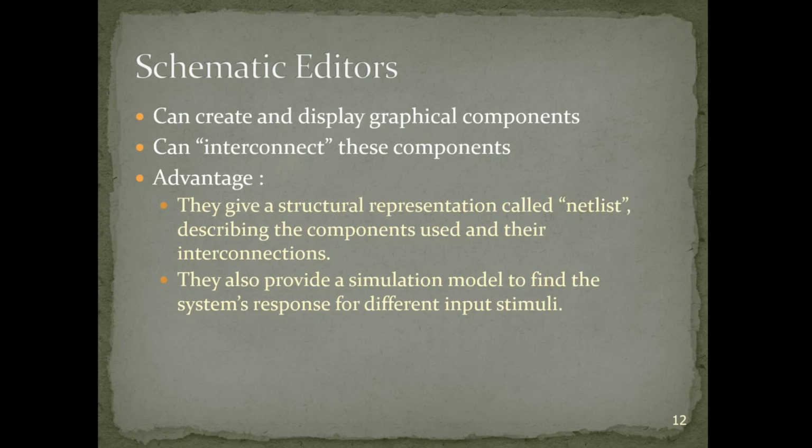What is also useful in Xilinx is that all those components that we put on a worksheet come with a library that can be used for simulation. So basically, once we have the schematic on the worksheet, we can also perform a simulation for it using a test bench. A test bench is basically the way Xilinx can provide the inputs for a design in order to simulate it.